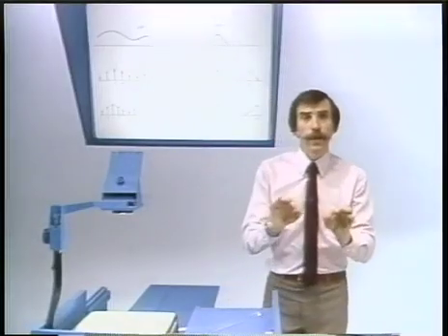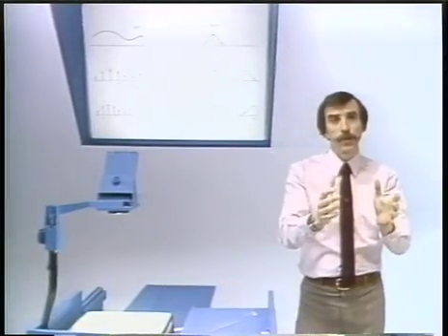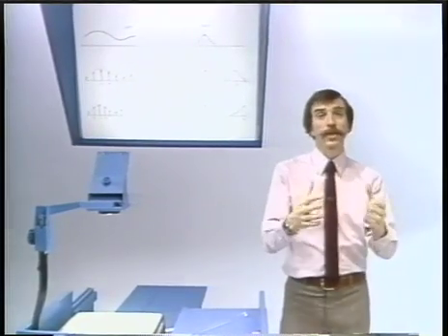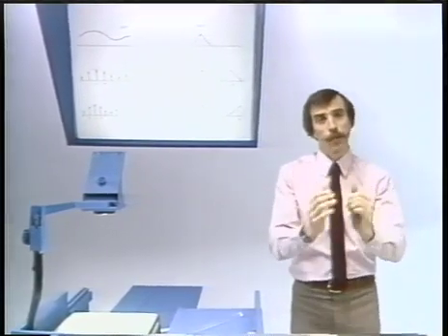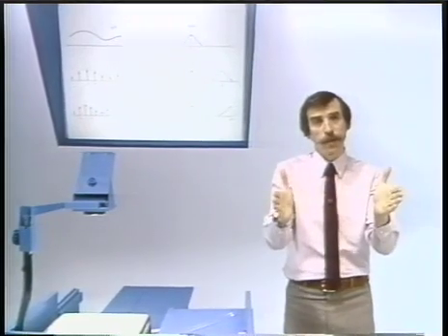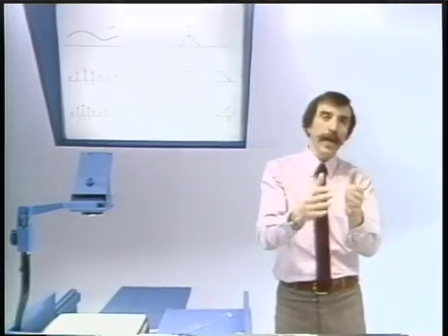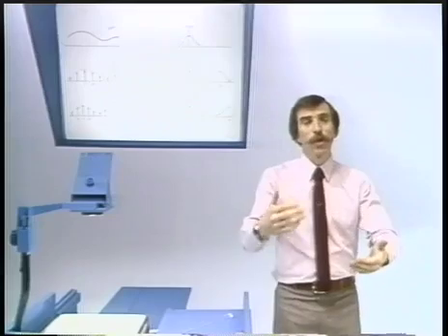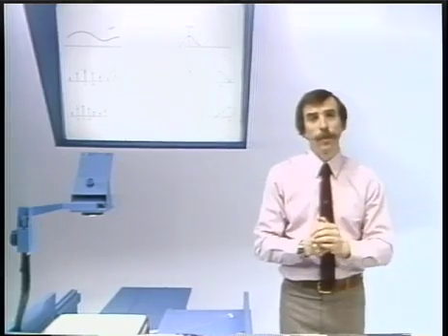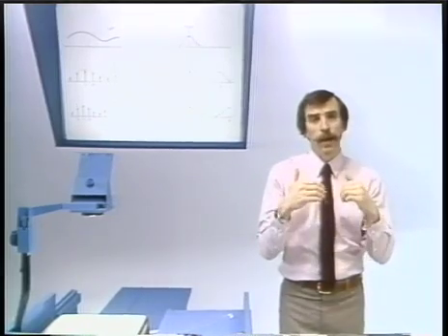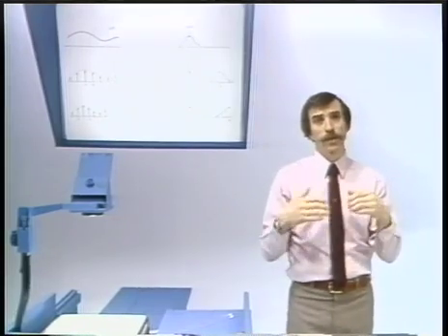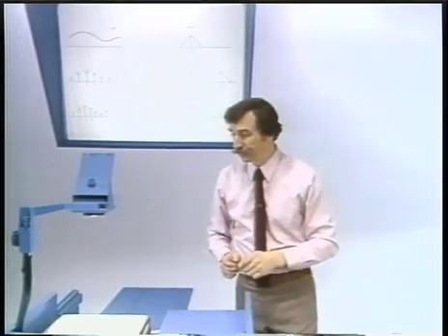However, in converting from the samples to the sequence values, we go through another step. What's the other step? The other step is a time normalization, where we take the impulses which are spaced by the sampling period and we rescale that essentially in the time domain to a spacing which is unity. So we're dividing out in the time domain by a factor which is equal to the sampling period.